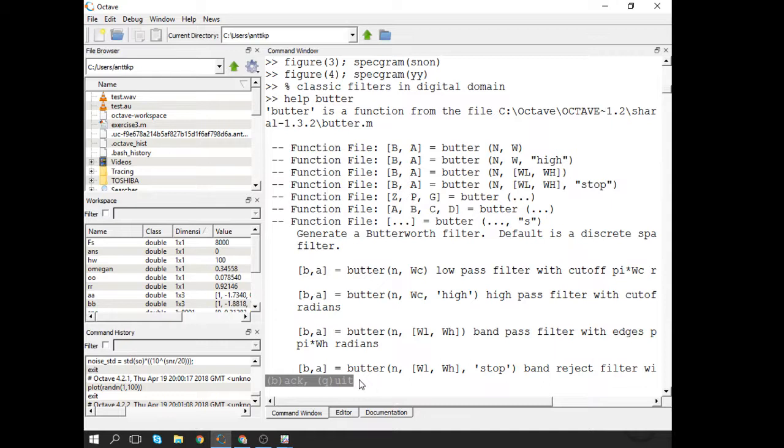Guess what happens to that one when you are warping the frequency space? It's totally destroyed. Yeah, we're losing the linear phase response totally. Okay, then there's elliptic filters which I usually use on these filter banks, that kind of stuff. But anyways, Butterworth and Chebyshev type 1 are the most common ones. Let's see, the Chebyshev 2 is also done. Yeah, but anyways, those are the classical filters.